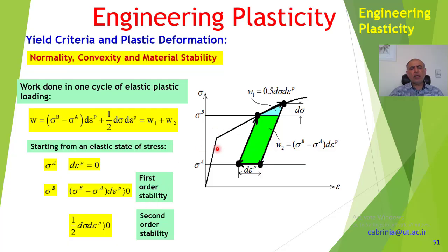Because we are in the strain hardening region, this must be positive. But if we go to the UTS, ultimate tensile strength, then that would be 0. And when we move outward from the point of stability or UTS, then it will become unstable, and this becomes negative in fact. Okay, so that is our understanding of the stress strain curve and the elastic plastic deformation.